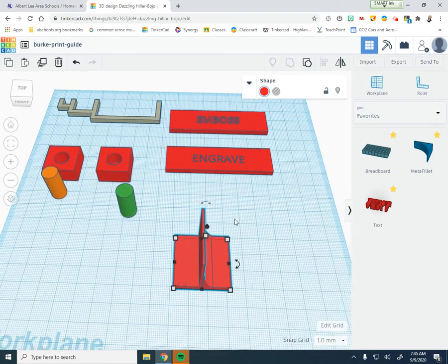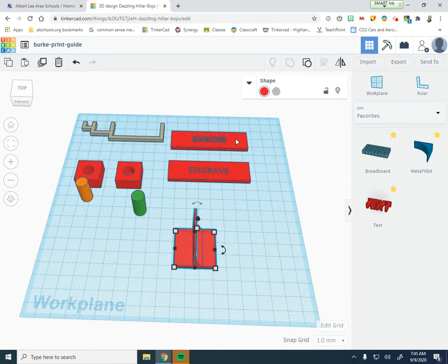So this is what you should turn in. You're going to export this as an STL and turn it in. Orientation, an axle through an opening, a model that will fit inside another model with a 0.5 millimeter difference, embossing, engraving, and fillets. That is everything that you need for basic printing to get us moving forward.